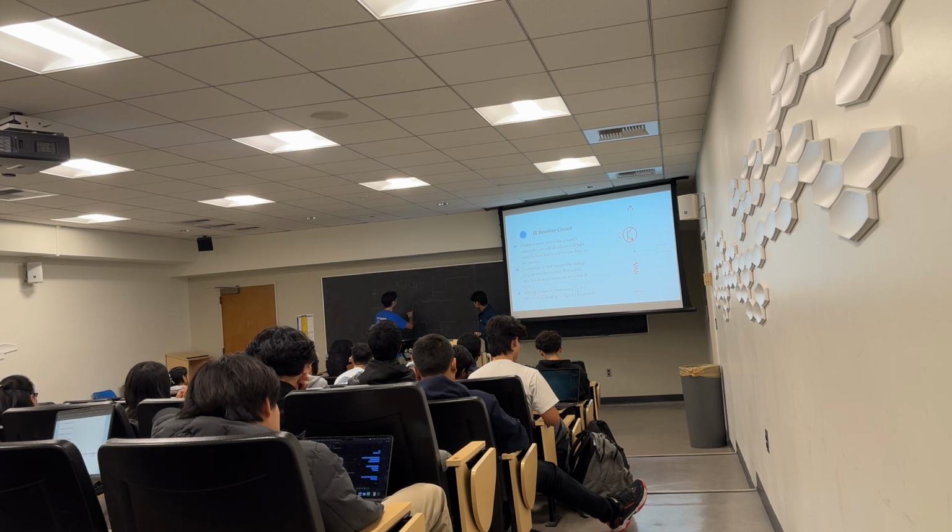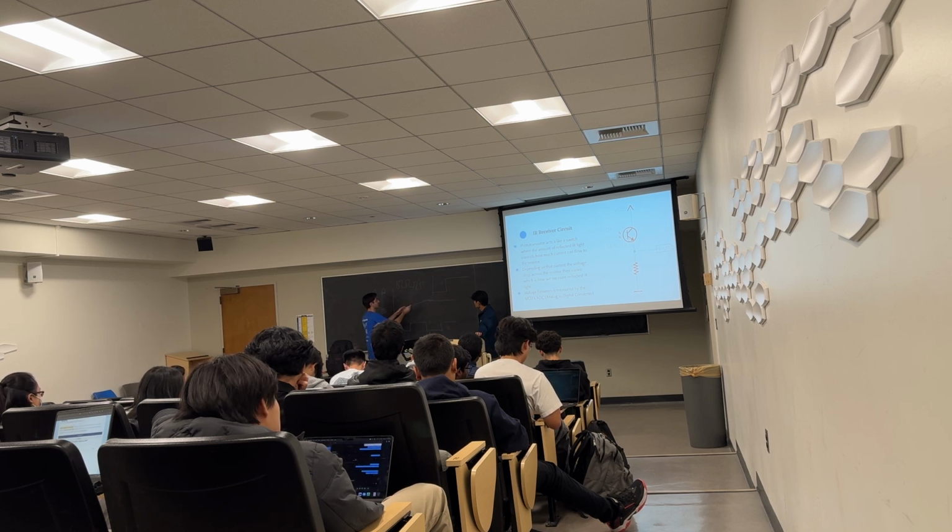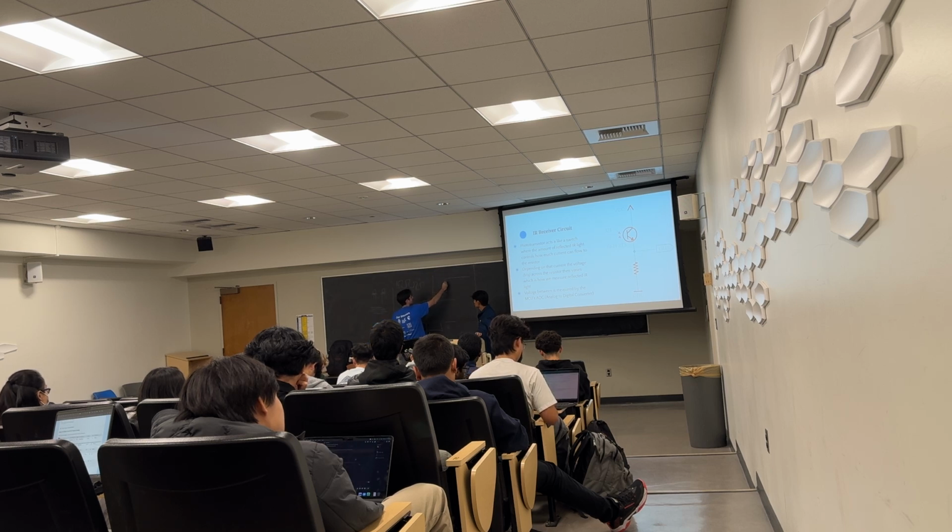Which in this case works out pretty well. But what if it was something like this, which was a slope? In the actual microcontroller, if you give it something like this, it doesn't actually know anything. It just has some arbitrary cutoff point, like right here, which says okay, this counts as a 1 on this side, and it would count it as a 0 on this side, which is not helpful at all. We want to have way more precision than just a 0 or 1.